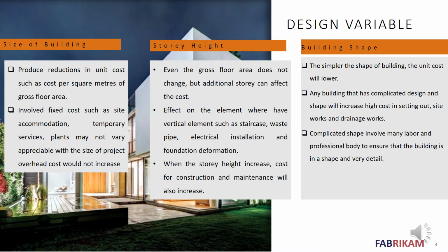The second one is the story height. Even if the gross floor area does not change, an additional story can affect the cost because there are vertical elements such as staircase, waste pipe, electrical installation, and foundation deformation. Construction maintenance will also increase when the story height increases.